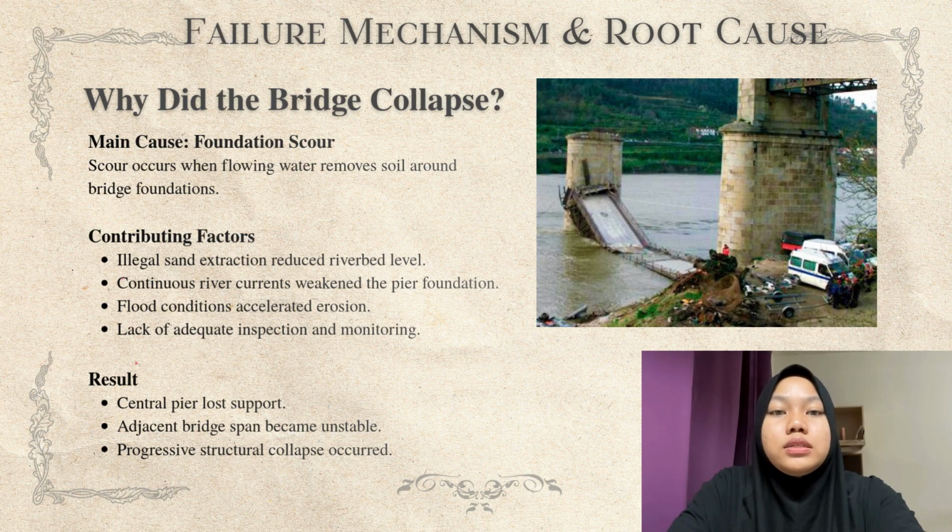First, illegal sand extraction lowers the riverbed level. Second, continuous river currents gradually weakened the pier foundations. In addition, flood conditions accelerated the erosion process. Finally, insufficient inspection and monitoring failed to identify the increasing risk.